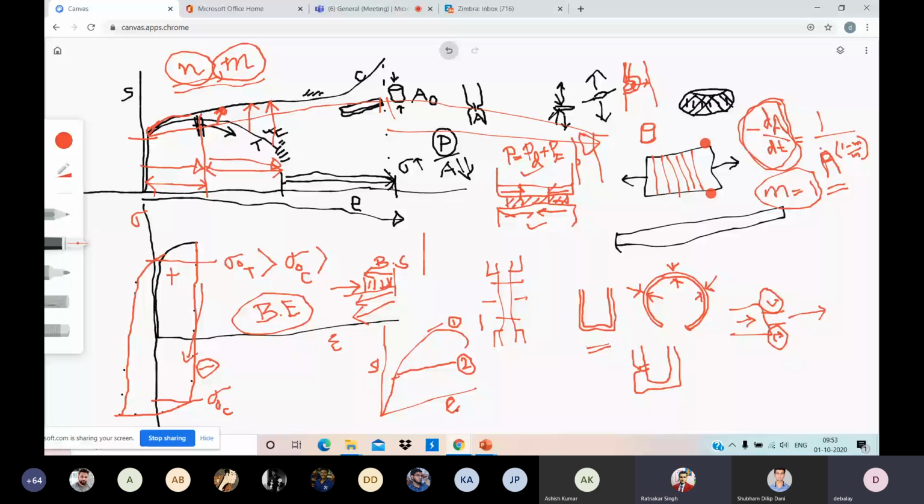Suppose uniform elongation you are getting even in curve 2, somehow it's flowing in a viscous manner, so uniformity is maintained even in 2. But why will you prefer the first one? Sir, in the first, it will give an indication before fracture.